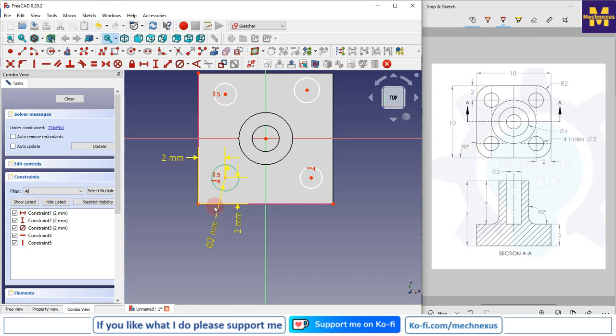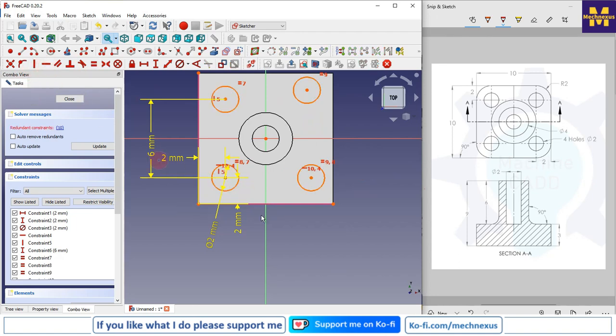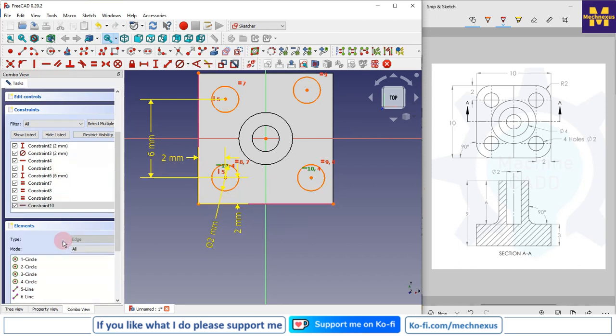So 2 and 2 is 4, so this distance would be 6 mm, so I will give 6 mm here. And now this circle and this circle are equal, so I will give the equal constraint. Similarly, I will select all three circles and give the equal constraint. And now I will select this one and this one and give horizontal. Here is a conflict, so I will delete it. This one and this one should be vertical.